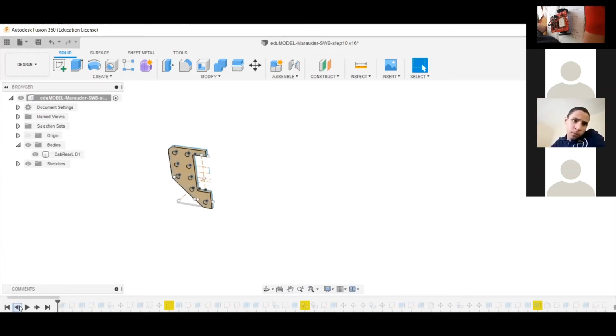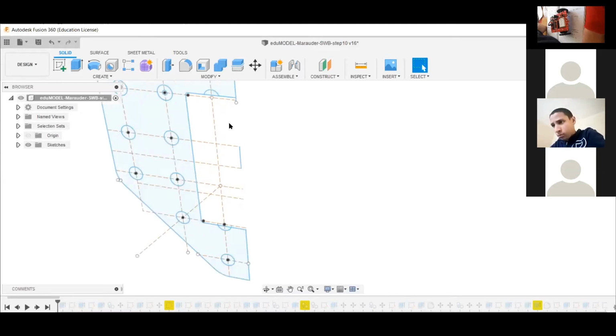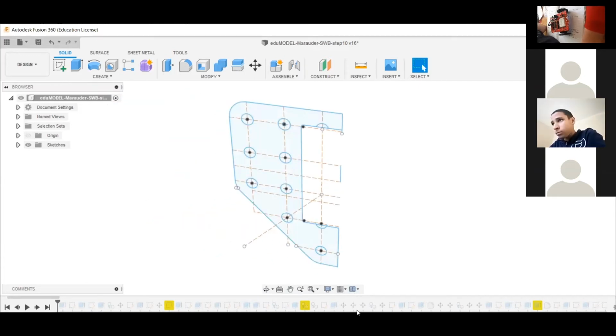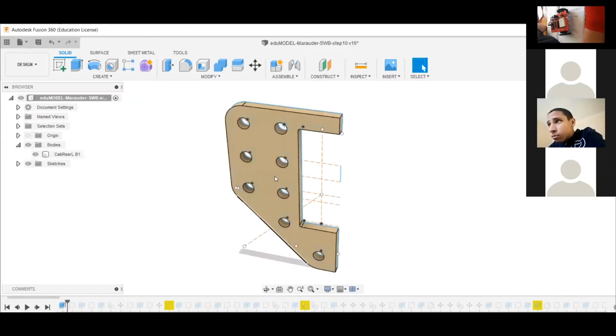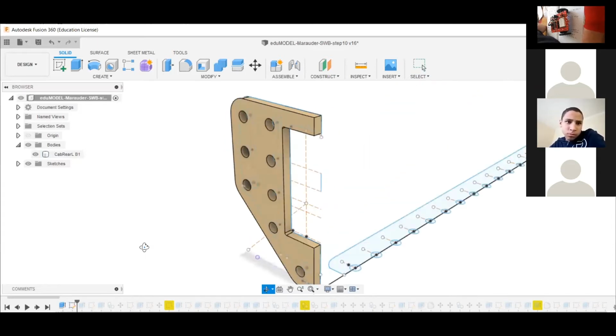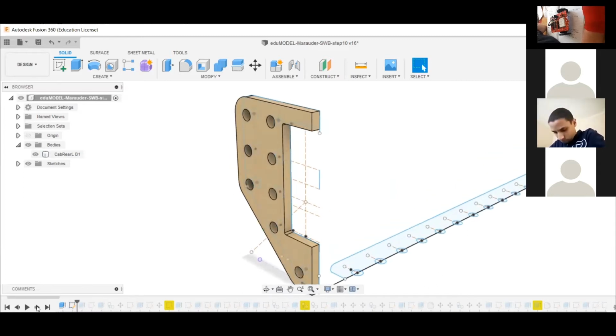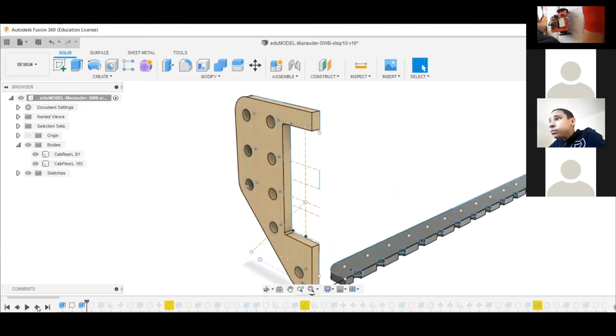Now that was an important step, because what you're seeing there, I'm just going to enlarge, and you'll notice now this thing you're looking at here is called a sketch, and the sketch is basically the underpinning of a solid model. So you draw the sketch, and then the next thing you do is you extrude a solid. So there's a solid. If I want to 3D print this part, I can do that. Now you'll see there's a new sketch in a different plane. This is in the Z up and down plane. This is in the X and the Y plane. So this is a three-dimensional model. I've added another sketch there, and then I've extruded it into a solid.